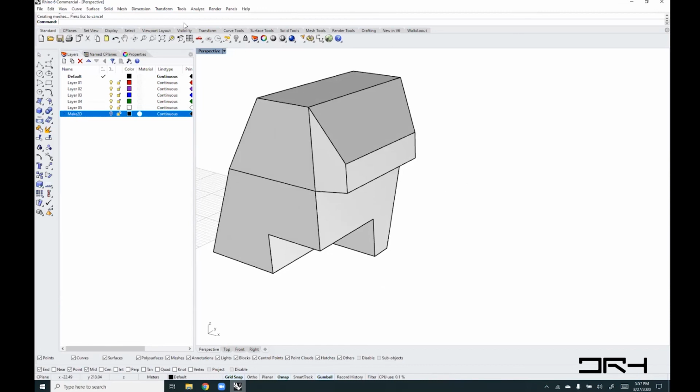And many of the commands, you can guess their names by just typing that. Anything that includes, for example, Boolean will be auto-completed once you type the word Boolean. So these are the different Boolean commands, right? And the other ones are when Boolean is not the first word in there, or it's related to Boolean. This is another way to remember. Remember when we talked about wire cuts, for example? If you just type wire, it auto-completes that. If you want to do an extrusion, just type extrude and it will auto-complete anything that does extrusion. For example, extrude surface, extrude curve, extrude a surface to a point, extrude a curve tapered, extrude a surface tapered, and so on. So this is a really good way to explore, just by guessing certain things.